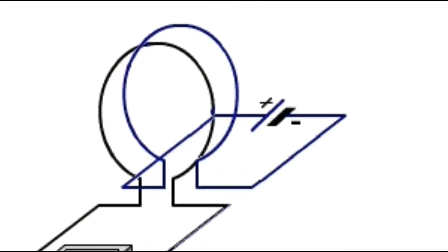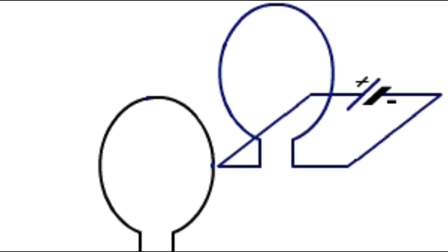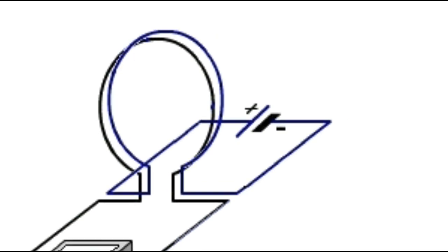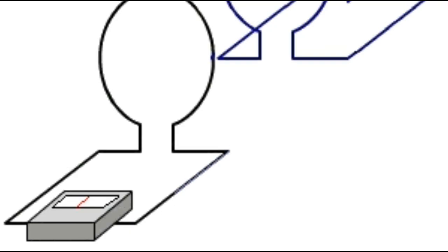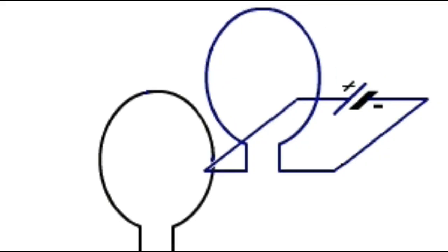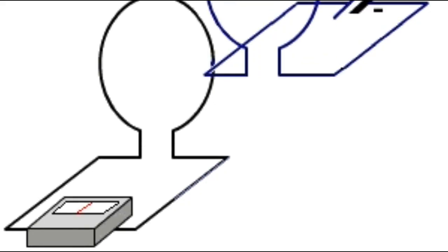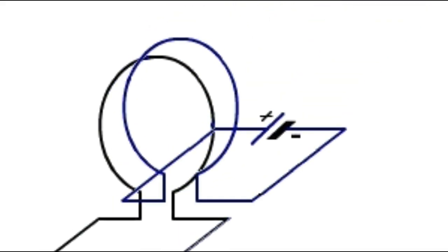With a steady-state DC current flowing through the inductor and therefore zero induced voltage across it, the inductor acts as a short circuit equal to a piece of wire, or at the very least a very low value resistance. In other words, the opposition to the flow of current offered by an inductor is very different between AC and DC circuits.